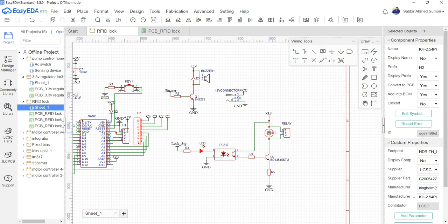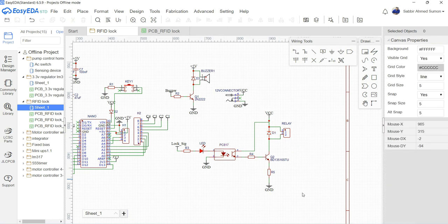And there is a diode. This can be a 1N4007 model diode, or it can also be a 4148 high speed switching diode. Whatever, this is a flyback diode. What a flyback diode does is protect the circuit from the relay when it's turned off. There is surge current or back EMF, which risks the external circuit. So it actually shorts the path when the relay is turned off and protects the external circuit.